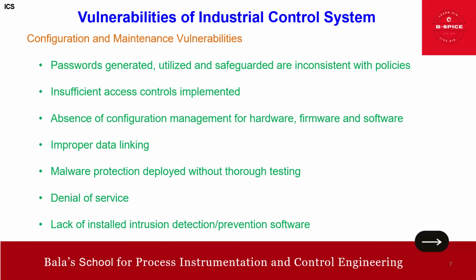Then lack of installed intrusion detection and prevention software. As we all know, an incident can result in loss of system availability and integrity, right? Data capture, modification, deletion, everything. Here, IDS or IPS, intrusion detection or intrusion prevention software, may stop or prevent various types of attacks, including the DOS attack, denial of service. So IDS and IPS software must be tested before deployment to determine that it does not compromise the normal operation of the ICS. So that point also we need to note.